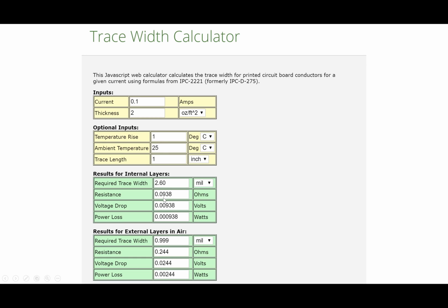Notice as well, if I look at that, the resistance of this guy is lower. We would sort of expect that a wider wire, a wider trace, would give us a lower resistance. Now, if you notice on the top, it's a skinny guy, and he has a higher resistance. Well, notice the critical thing that we set here, the critical specs that we give as inputs, is how much of a temperature rise do I want to have?